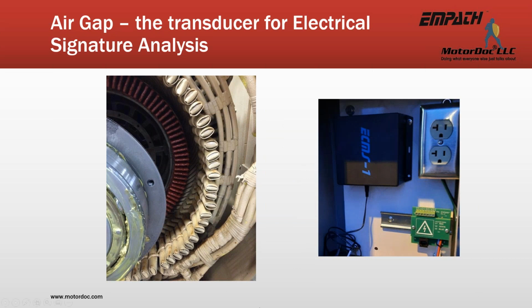But in any case, the transducer for electrical signature analysis is right in between the rotor itself and the stator. That air gap right there, the magnetic field, is the transducer, not the rotor, not the stator. We take our readings off the stator, but the details are from that air gap. That, by the way, does include transformers. So on the right, that's an ECMS1. That application there is actually not in a turbine. That is at a factory connected to their utility meter. We have a revenue grade of 0.2.